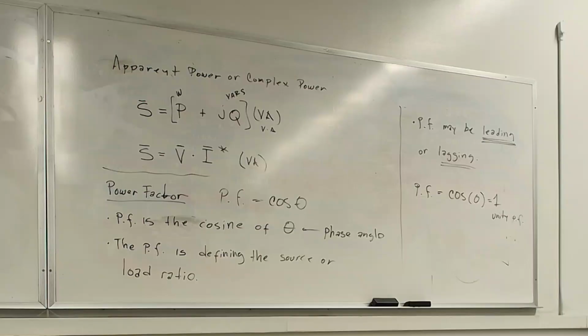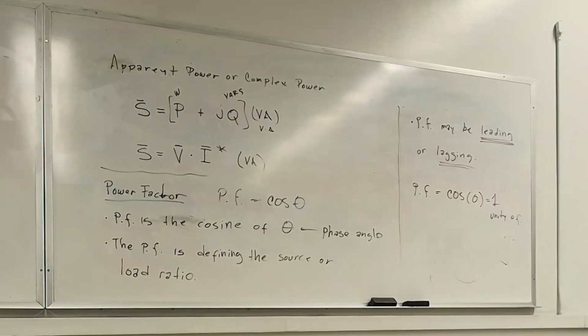Let's go back to voltage and current and real power for a second. If I say that the phase angle, the angle between the voltage and the current, is zero, what kind of load am I dealing with? Resistive load. What kind of power am I dealing with? Real power, right? That's what I want. That's what the utility wants you to consume, because that's what you're really paying for, quote unquote paying for. We'll come back to this.